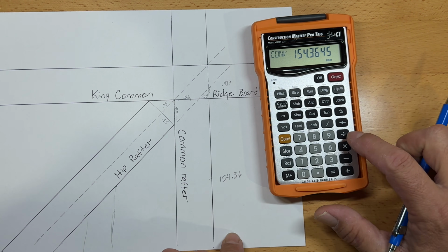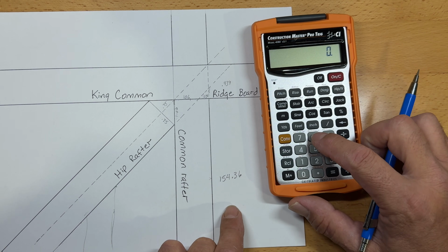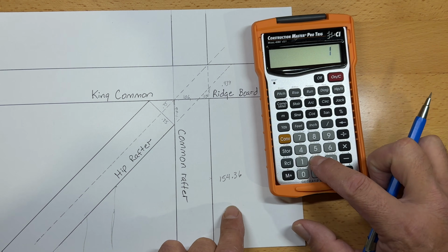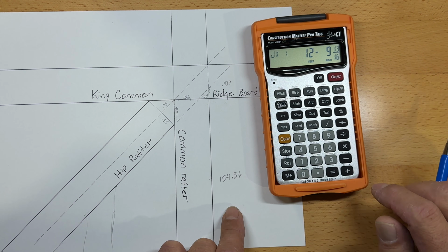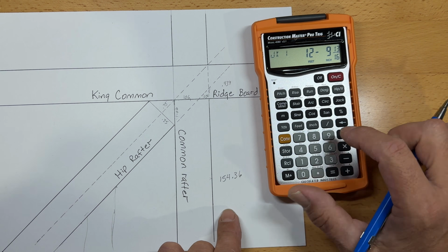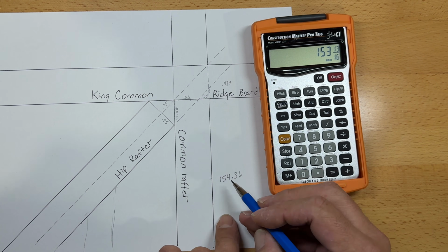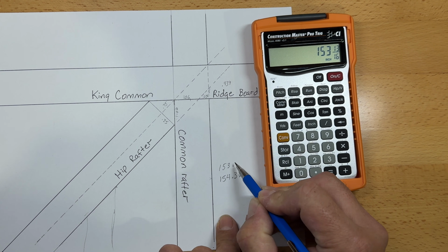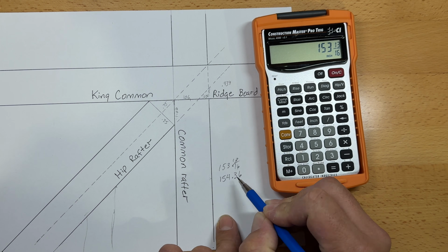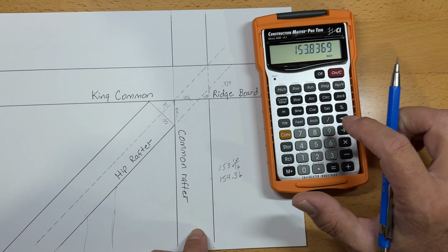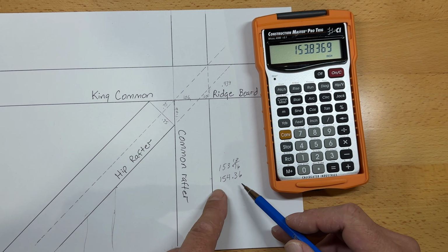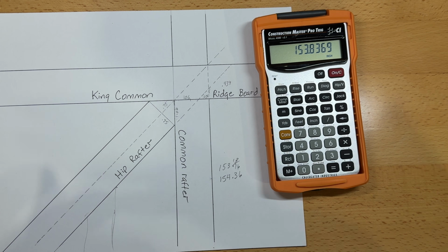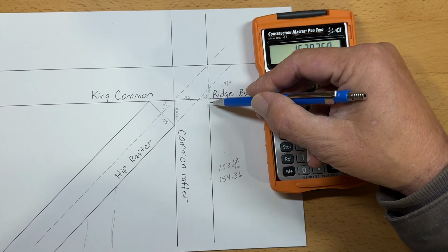So let's clear this out. I forget what the original measurement was. We'll do 8-inch pitch, 12-foot run, and then hit our jack rafter. And the original was 12 foot 9 and 13/16. We hit inch. That was 153 and 13/16. So you can see that if we hit it again, I think I'll put it in decimal. 153.83. So you can see that there is about a half inch. It varies as the pitch changes. It's going to change how far this number is off.